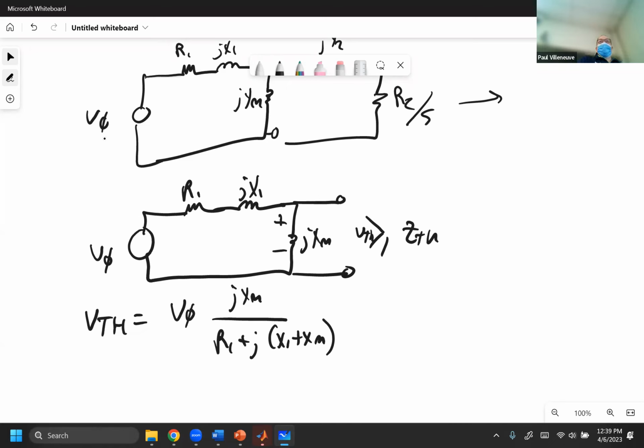Anything that you hadn't seen before? It's ringing a bell. Okay. I'm not trying to be sneaky. I want to make sure everybody understands. I don't throw away the R2 and the X2. I'm setting those aside because I'm just trying to find the Thevenin equivalent. And I can take any part of the circuit I want, isolate that part, find the Thevenin equivalent, and put that back in, and I'm going to get the same results. That's the concept of Thevenin equivalence.